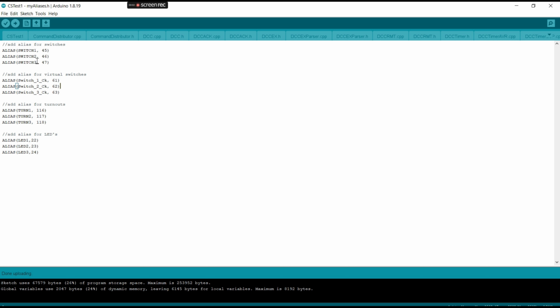Everything else is the same, and for those who weren't there for the first part, we're just giving names to stuff so that when we write the script, we don't have to remember numbers, what's where. So we're giving everything an alias, a name. So alias says, hey, we're giving something a name. Then what is the name? In this case, switch 1, and then we're giving it an address. And in this case, 45. That's the Arduino pin 45. So switch 1 will be read on pin 45. Switch 2 on 46. Switch 3 on 47.